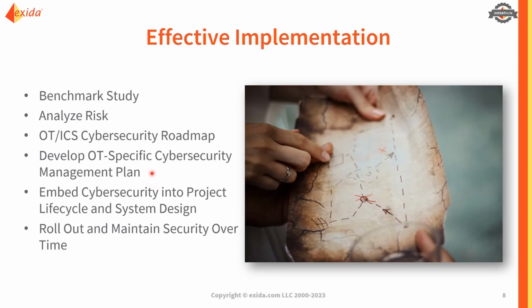From there, it's important to have a cybersecurity management plan or an overall system. And we really highlight it being OT specific because although there's a lot of great things that we can leverage from the IT side, because the risk is on the OT systems, there needs to be an OT specific understanding and also OT ownership. And so these OT procedures may sit under the overall IT umbrella. They may be managed by a group that's led by IT. But it's important that we really make sure that there is information specific to OT systems and the approach required for OT environments as part of that cybersecurity management plan.